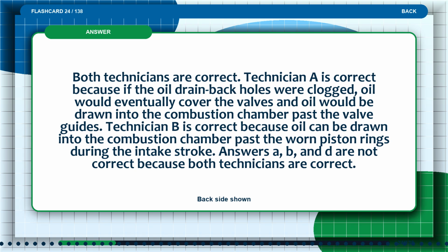The answer is both technicians are correct. Technician A is correct because if the oil drain back holes were clogged, oil would eventually cover the valves and oil would be drawn into the combustion chamber past the valve guides. Technician B is correct because oil can be drawn into the combustion chamber past the worn piston rings during the intake stroke. Answers A, B, and D are not correct because both technicians are correct.